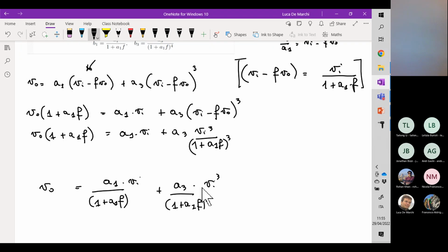So even when put in the feedback loop, we have this new omega null, which is much smaller than the original one. But nevertheless, this situation is most favorable in terms of stability. Okay, so stability is typically a mandatory request for our circuit. So that's the reason why it's even more important with respect to having a very large band. Okay, so this compensation strategy is called frequency compensation with dominant pole.